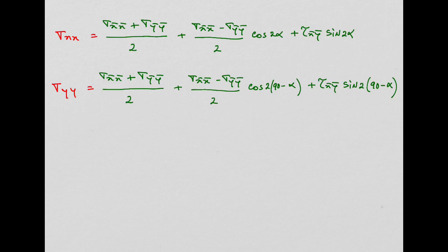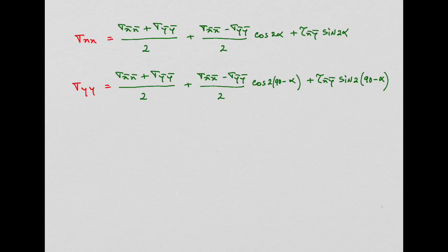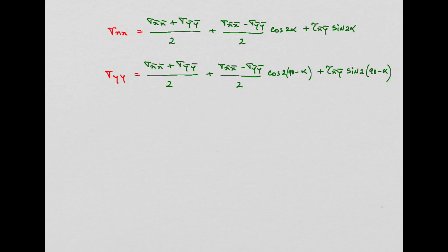And why am I putting it this way? Because the next step is quite obvious. I can even do something more here, because we know sigma xx is equal to pressure times the radius over 2t, and sigma yy is equal to pressure times the radius over t.